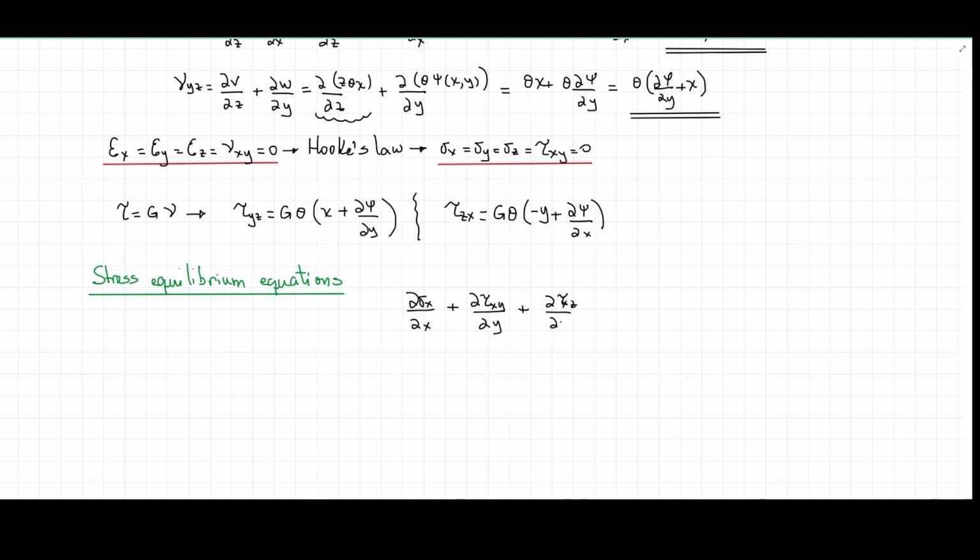And then I'm going to neglect body forces, because there are none acting on the element, and that's why the other term, this b, if you remember, is not going to appear here. I'm going to continue with this one. I'm going to have this reciprocal here. I can write it in the same fashion because we already know that tau xy equals tau yx because of the reciprocity of shear stresses.